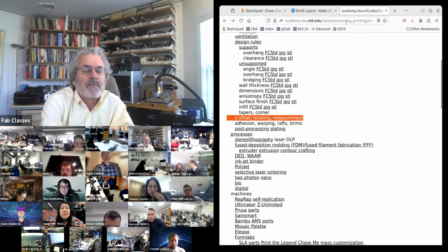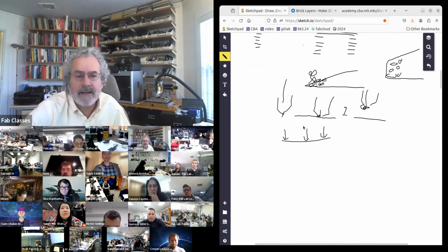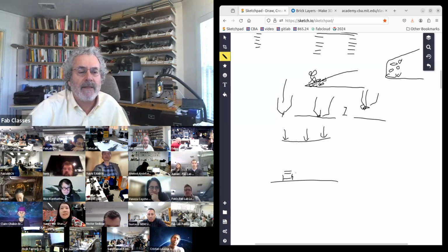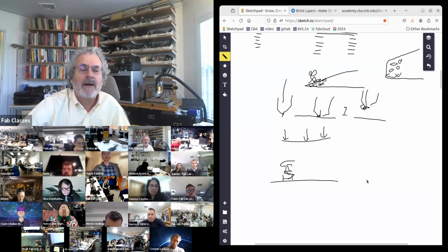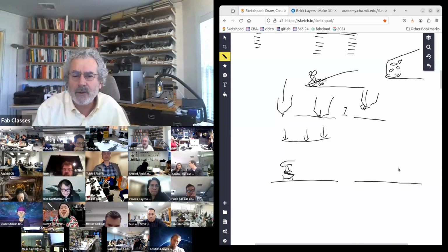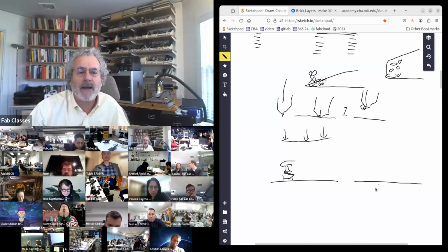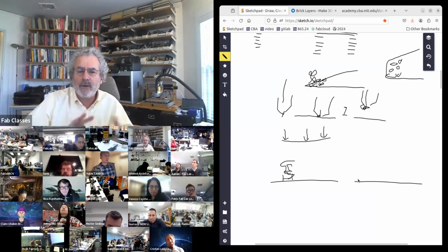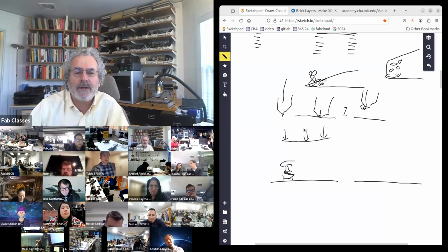Even then, depending on what you're printing, if there's bad adhesion between your print and the bed, as you're printing, eventually it can come off and you get spaghetti again. And so there's a number of things you can do. Some people use an adhesive layer. I don't recommend that because the adhesive becomes sticky and gooey and accumulates. I prefer the opposite, which is to make sure the bed is completely clean, to remove all the oils and any residue on it.